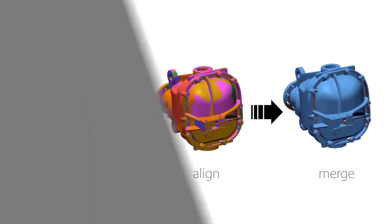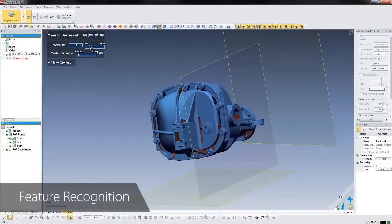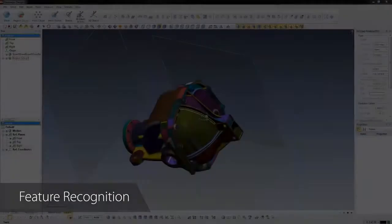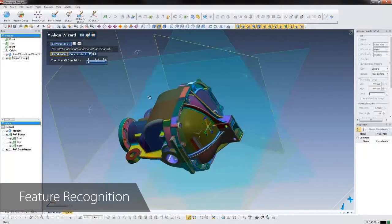To facilitate the scan-based design process, Design X automatically recognizes the different geometric regions that make up this part, and applies colors to them so we can easily select these features and use them to speed up the design process. The feature regions will help us align the scan to the global coordinate system using the alignment wizard, a key step to making a good CAD model.